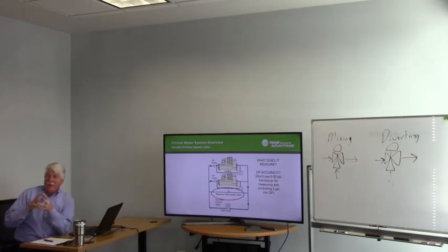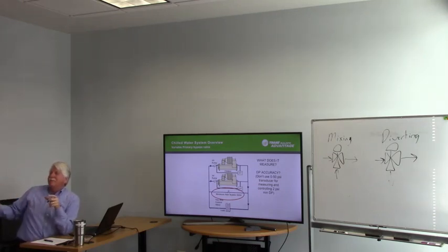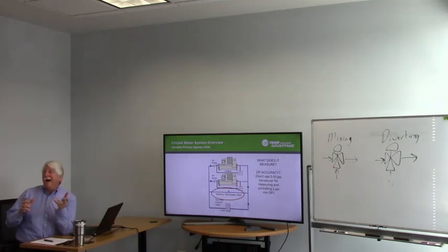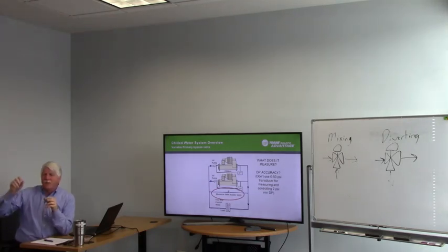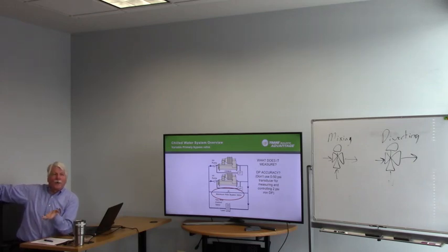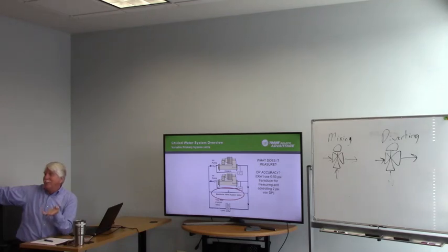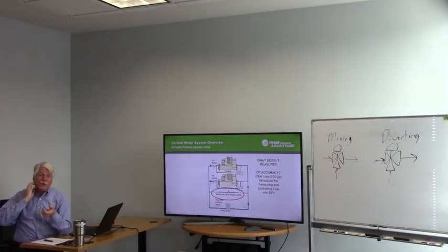Have you guys seen, anybody know what a traditional centrifugal chiller at minimum flow, what kind of DP it'll have? Very low. It's usually never more than 2 pounds. A lot of times it's a pound, okay, which is very low. Now, if we put a 0 to 100 pound transducer on that thing, how well is it gonna work when we're trying to control at 1 pound? It sucks. 0 to 50 sucked.